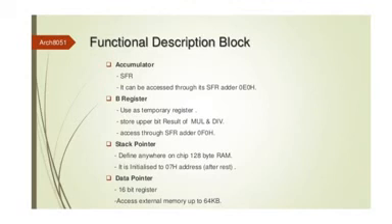On the stack, whenever I want, I can store some data or some address, or else I can retrieve that data and address from the stack. How does the operation work? Before that, I said first it will point towards 07H. After the reset operation, the stack pointer is initialized at 07H.